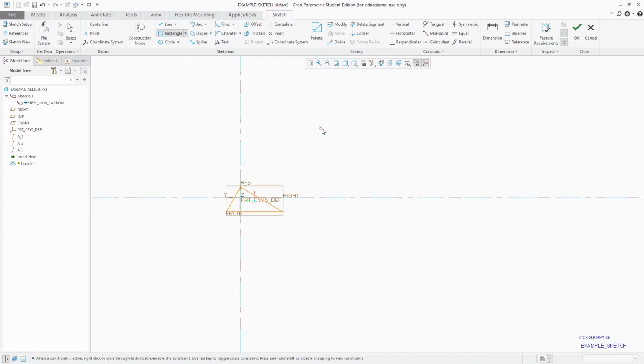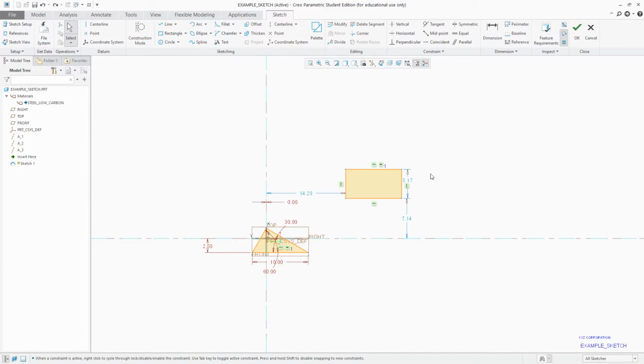Click at any place and drag it and make an appropriate rectangle. Like now again, click left button of mouse. So now we need to press escape so that we can exit from the rectangle tool. Now we can give it a dimension, like for example I want to make it 6, and here you can see the dimension is being controlled by a constraint, so I will be deleting it. I will be talking about constraint later on, and let's just make it 12.